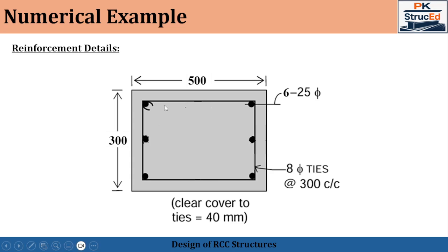Okay. So here, this reinforcement ensures that the column can safely resist the axial load, the moment capacity is adequate, and the compression failure is avoided. And the purpose of the ties is to prevent the buckling of the longitudinal bars. It will confine the concrete core as well as improve the ductility. Here the detailing is as important as calculation because improper detailing may lead to premature failure, buckling of bars, as well as reduced strength.